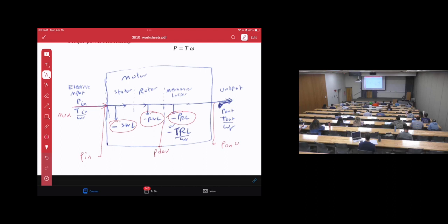So you need to keep in mind the development power is the input power minus electrical losses, which are stator winding and rotor winding. You don't need to subtract the rotational losses, because rotational losses are regarding the mechanical parts, while the development power is associated with what's happening at the end of the electrical parts without including the mechanical. Okay? So development power is only for the electrical parts. While the output power is related to what's going on after removing the losses, after the mechanical parts.